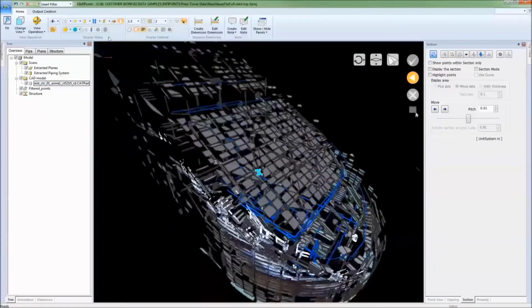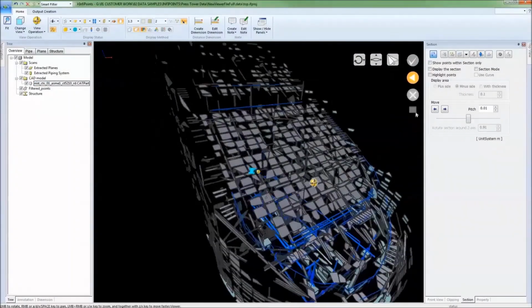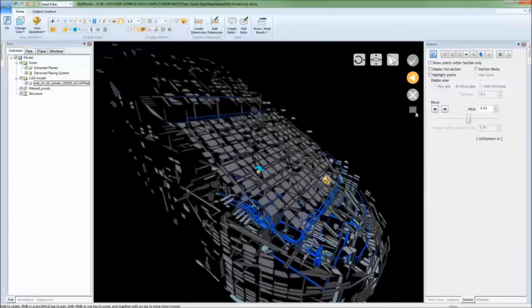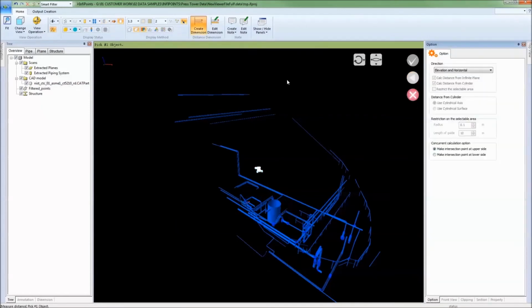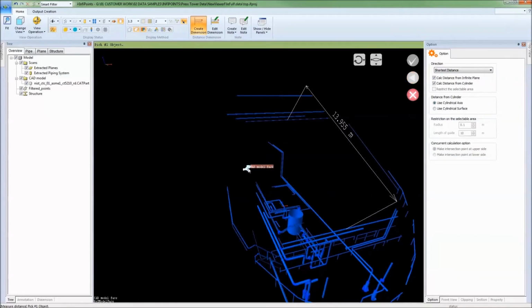Not only is the point cloud exported for viewing, but any CAD model, extracted or otherwise modeled features from the planes, cylinders, and steel structures, as well as 3D drawings and 3D dimensions are maintained in the viewer for collaboration. Along with maintaining what was created, the viewer file allows for additional 3D dimensioning, including dimensions between InfiPoints models, imported CAD models to the InfiPoints environment, as well as point-to-point from the point cloud.